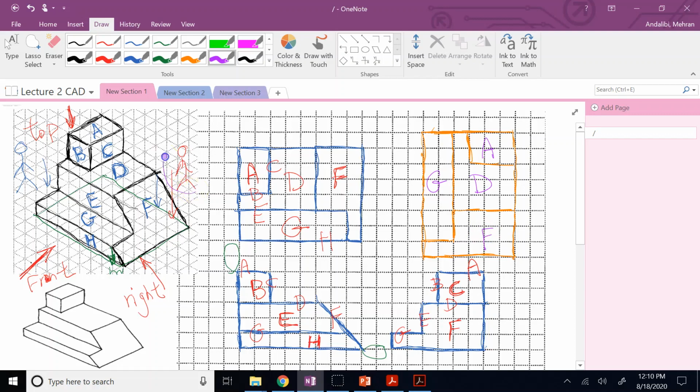So if you look with this person, you would see this, which is absolutely wrong. Because if you bring this guy and put it right here, then the front view and the top view cannot be vertically aligned. This is only 6 unit wide, this is 8 unit wide. So you cannot bring this and put it on the top of the front view.